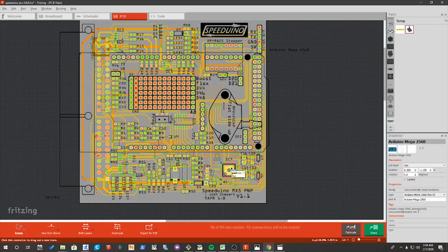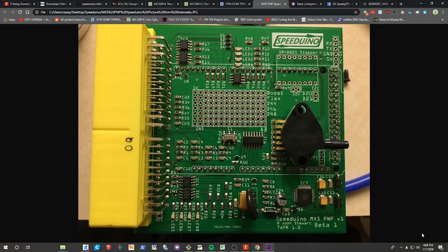Because, as we all know, key switch, the 12 volt switched power, was being brought in, but it wasn't turning into 5 volts. At that point, I was at a loss because I wasn't sure how I was going to fix this integrated circuit on this board, but I had figured out that there was an issue with it, and it wasn't supplying the 5 volts it needed to supply to the Arduino to actually power up the ECU.